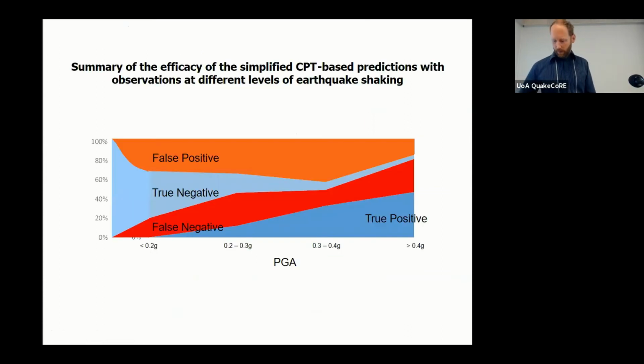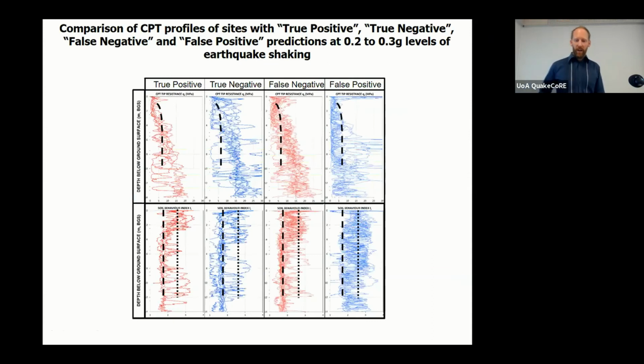And so, what we've learned from this study and research is that effectively anywhere where we see thick deposits of clean sand, where the soils have a lower density, even perhaps a density that sits above the reference line but some layers below, those are sites where liquefaction is occurring, and perhaps where things are near the threshold but there's a little bit of under-prediction occurring.